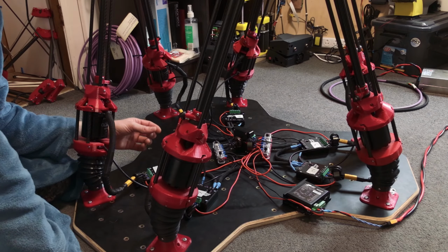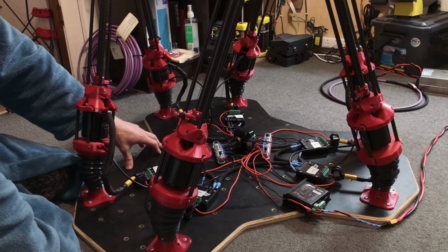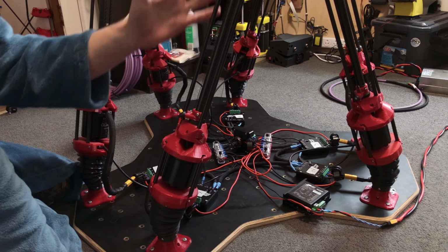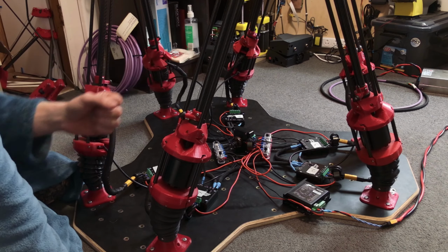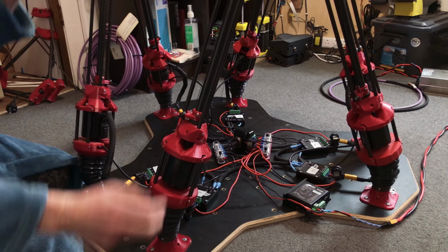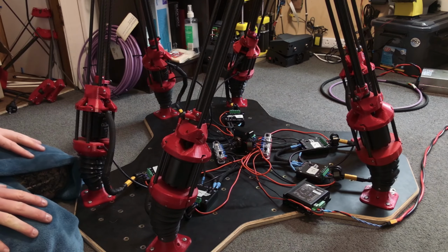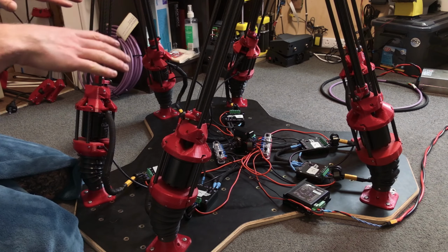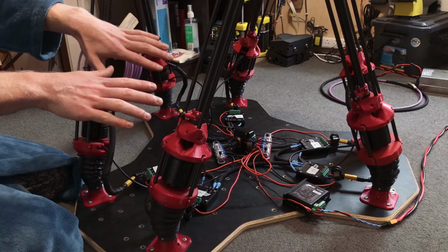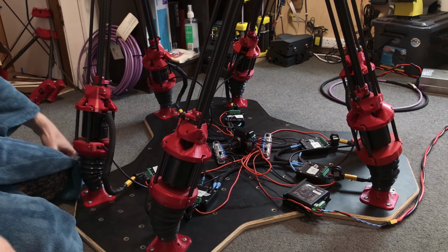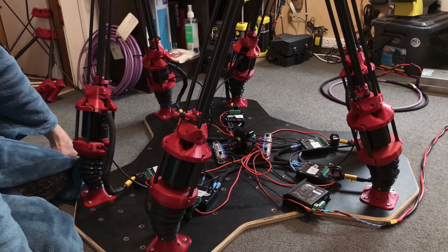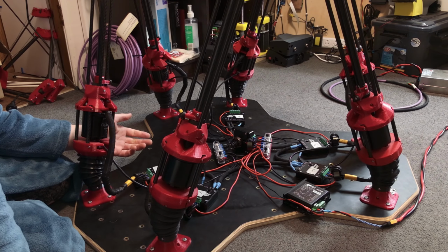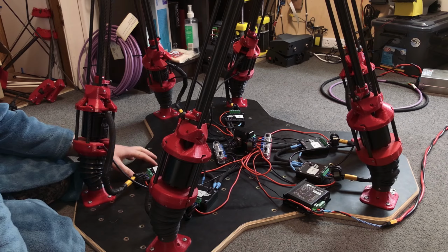So my second option is to run the entire system at the 21 volts of the hand motor, which is fine for the legs. It just means that they will be less punchy than they would otherwise be. But I think that should be fine because the whole platform isn't actually going to be doing a lot of work. Especially each individual leg is not really going to be doing that much work because it only needs to move side to side, while the hand motor is the one doing the main pushing. So I'm considering just making the whole thing 21 volts and then being done with it, but I don't know. I'm not sure.